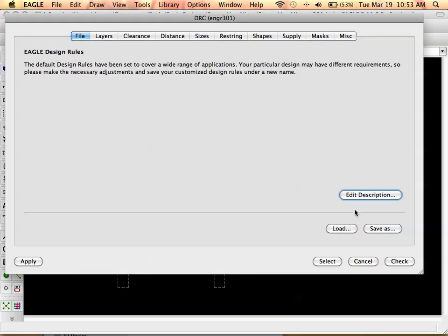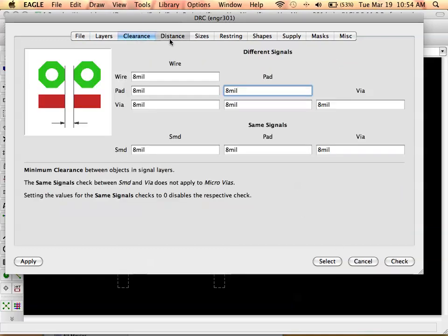But you now know about what it is, and should you want to design and have some more control over your design, then you can do that. Also, you're okay to change the DRU file if you make the tolerances looser, right? So don't make the board house work harder.